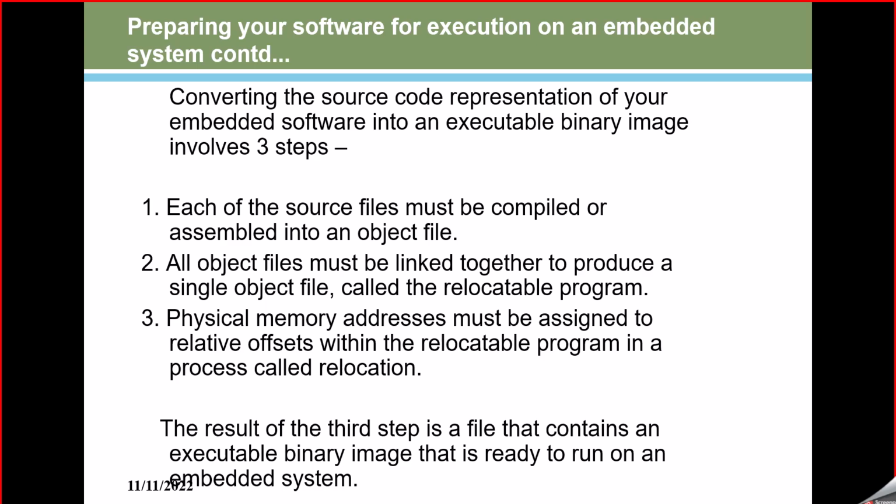So, how do we start writing a program? Basically, you need to have an editor and a compiler. Generally in embedded applications, we use a cross compiler. You write your program in the editing window, right? Then you save that program into a .c file, correct?